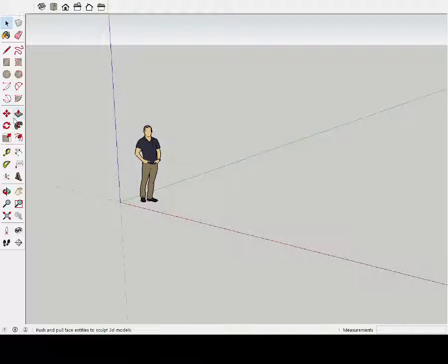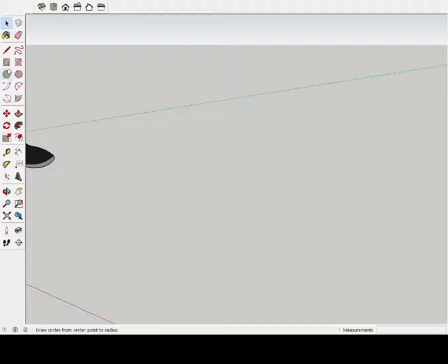Okay, so this is how you go about using SketchUp to create a drawer organizer. The first thing you need to do is zoom in. You need to use the square tool. The interface might look slightly different on your computer, and when you draw out this sort of rectangle on the floor, you can actually input the sizes before you click away.